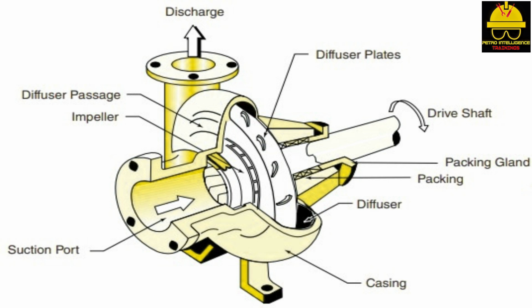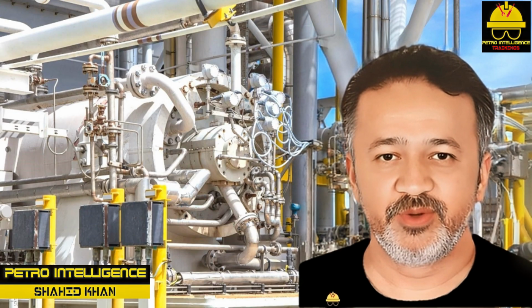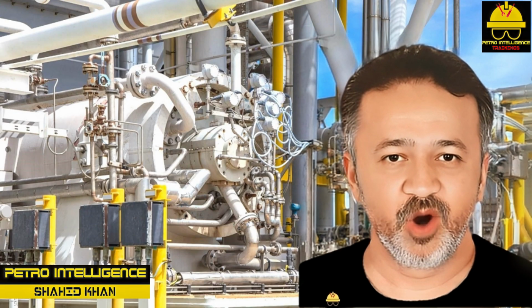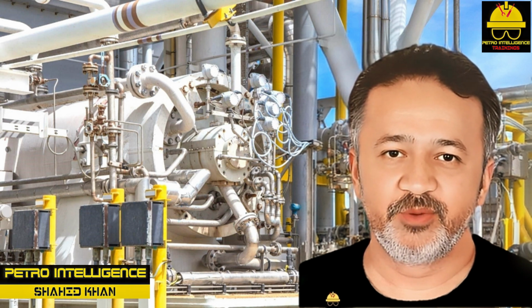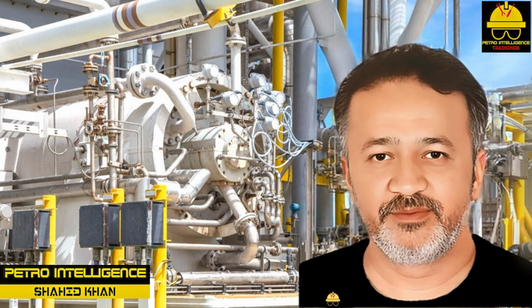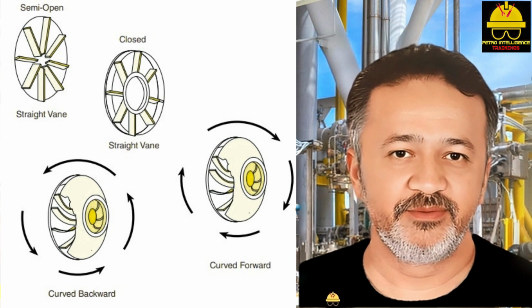The part of the impeller vane that comes into contact with gas first is called the suction vane tip. The part of the impeller vane that comes into contact with the gas last is called the discharge vane. The driver is an electric motor or turbine. The basic types of impellers used on centrifugal compressors are the open backward-bladed impeller, open radial-bladed impeller, and closed backward-bladed impeller. This picture illustrates various impeller designs.